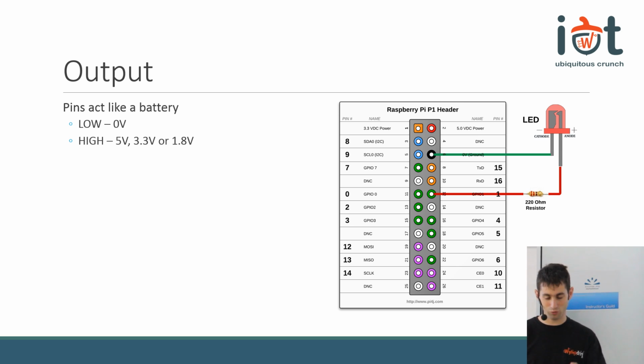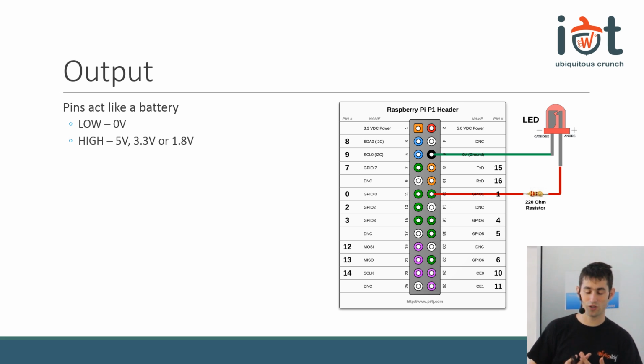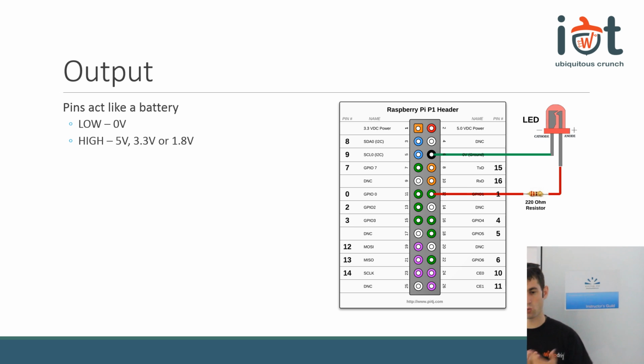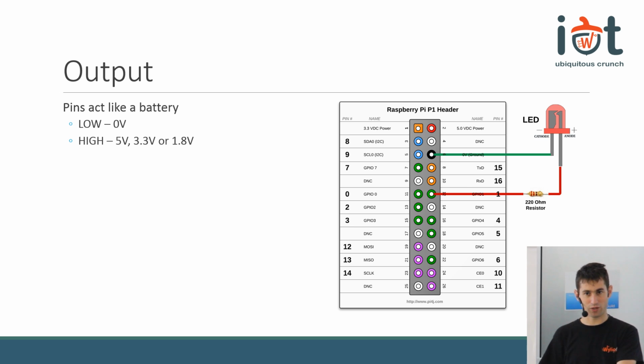It's very important to look at the schematics when you have a device and see how the LED was connected. So in no way does writing 1 on a pin mean lighting up an LED, or writing 0 on a pin mean turning an LED off.